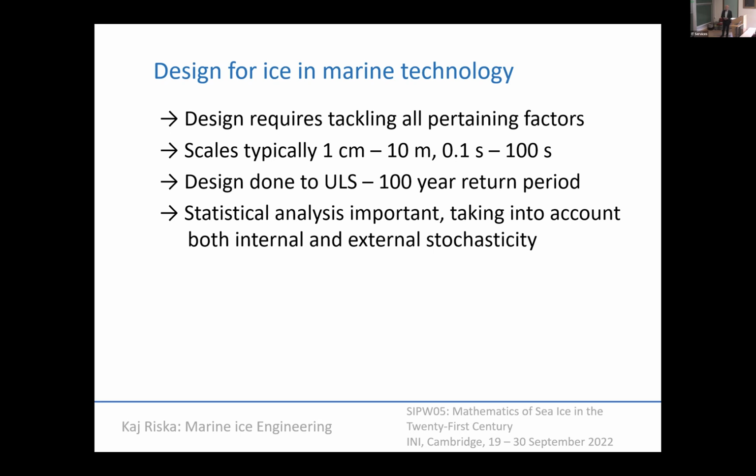Scales 1 centimeter to 10 meters, that's typical engineering scale, and 1 second to 100 seconds roughly. This is not to say that there are, of course, if you study cracks and if cracking is important, then of course the scale goes down, and also down both ends sort of on this. And then also you might say that there's also high end. I mean, design is usually done to ultimate limit state, which is 100 years return period prediction. So that's 100 years already. But engineering studies usually this is the scale where you are.